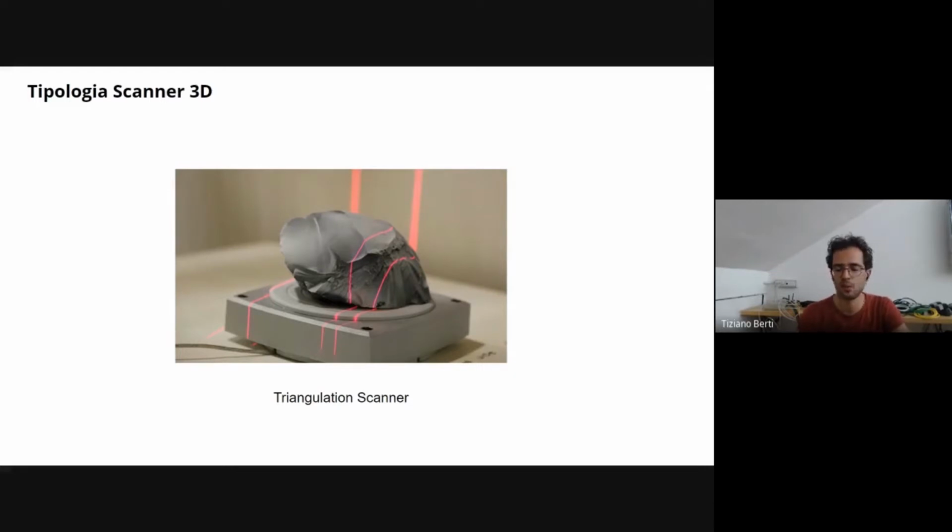If you want to do that with photogrammetry software and setup, it's fine to make a 3D scan of a very small object. You just need to be prepared to do a macro photography kind of setup. So it will be a bit more difficult to get a photograph of a small object, everything in focus, and so on. This kind of 3D scanning is slower than photogrammetry. Photogrammetry is a slow process too, but we will see there are some ways to make it fast.